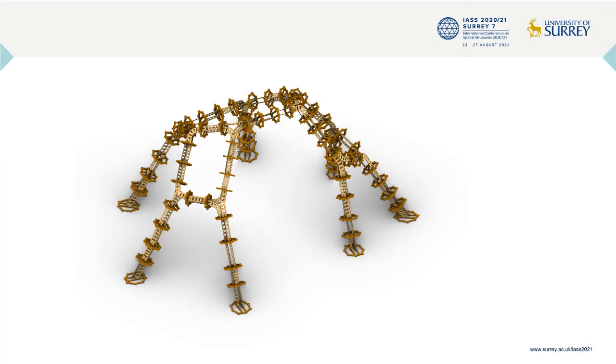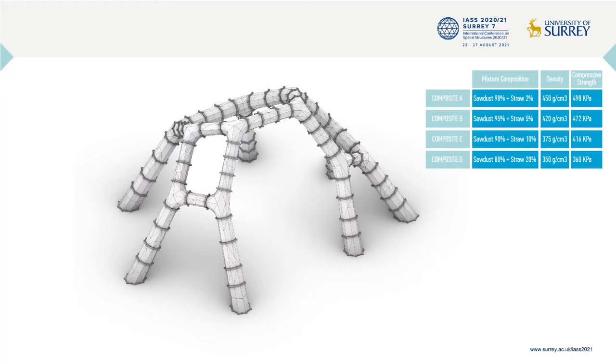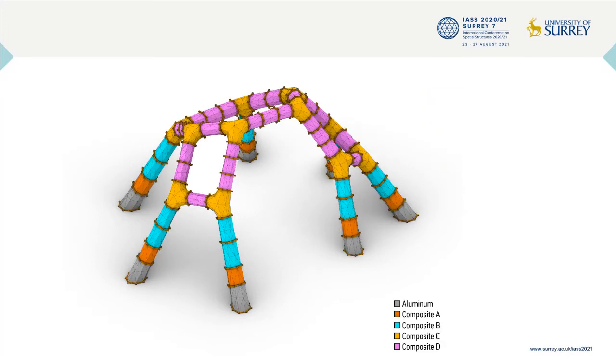The method that we developed contains an inner skeleton made of light birch wood. As mentioned before, we used 4 different grades of the material that we cultivated for different parts of the structure. You can see these different composites in this diagram. The stronger components are closer to the base of the structure, and the lighter components are used in the upper parts. To avoid the negative effect of capillary water on the structure, we used aluminum for the 7 base elements.